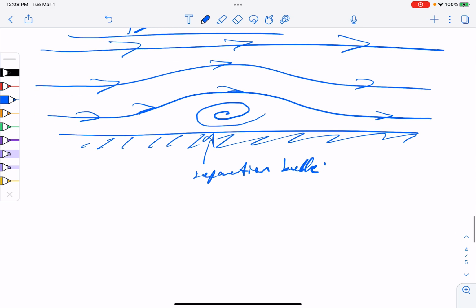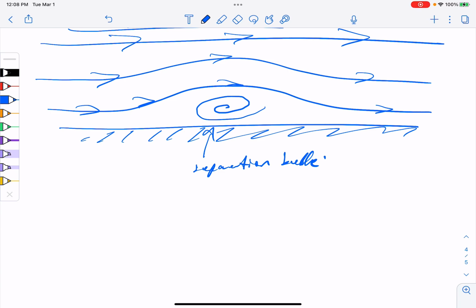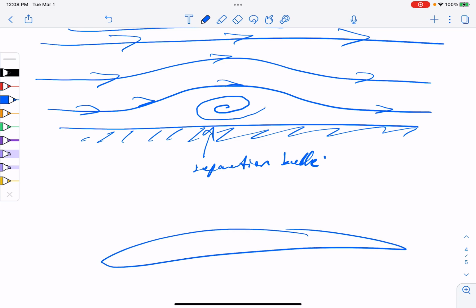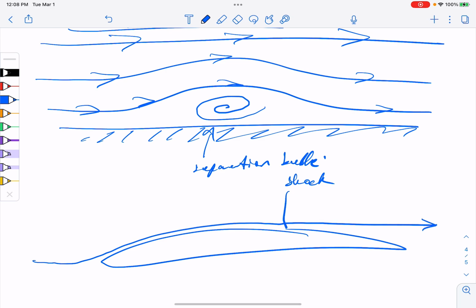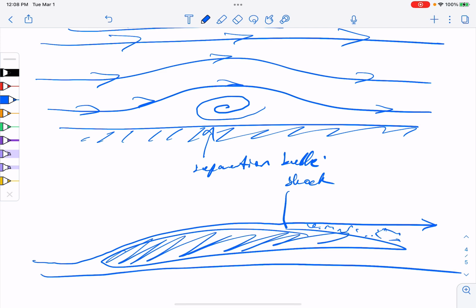Other things that might happen, which are trying to be accounted for, are, say, interactions with shocks. So if you have a transonic airfoil, which a lot of aircraft fly in that regime today, you might have a shock here. And the flow is attached at the wall, but then it comes off the wall like this because of the shock, and then you'll have a turbulence separation. There's the flow down here. This is an airfoil. So it's developed to try and handle those cases some too, but not always well.